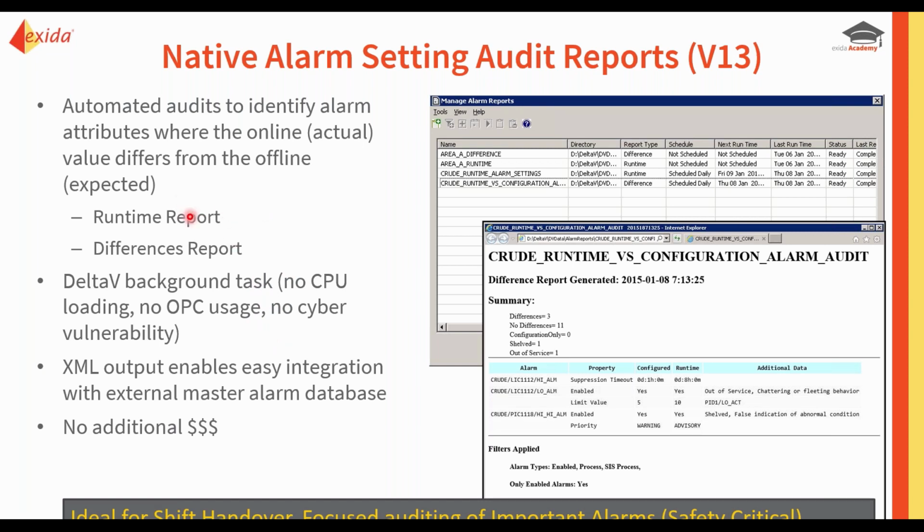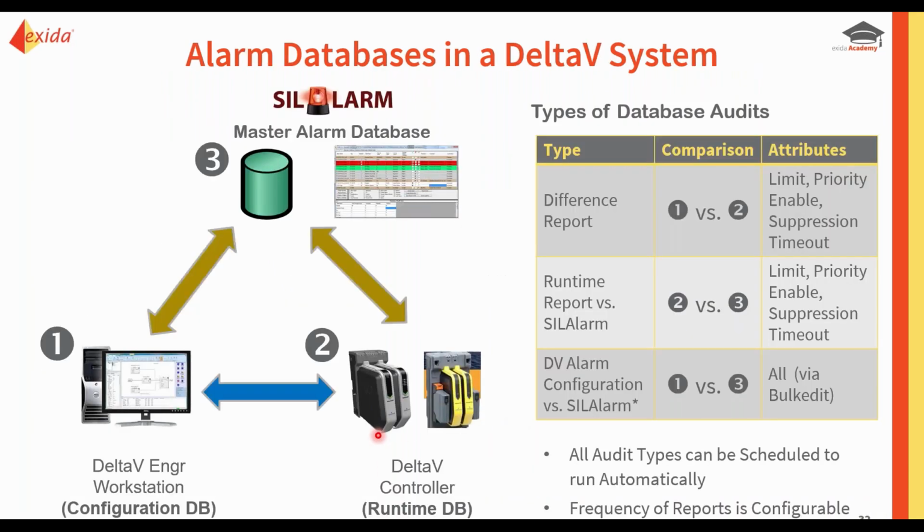The purpose of the runtime report is so that you can compare the results to an external master alarm database like SILAlarm. So that's why that audit report format was created, to be able to compare to an external database. So we're going to look in more detail about the different options. So in a DeltaV system with this kind of reporting, and if we were using a master alarm database like SILAlarm, there then are really three different alarm databases that we need to be mindful of and keep in sync.